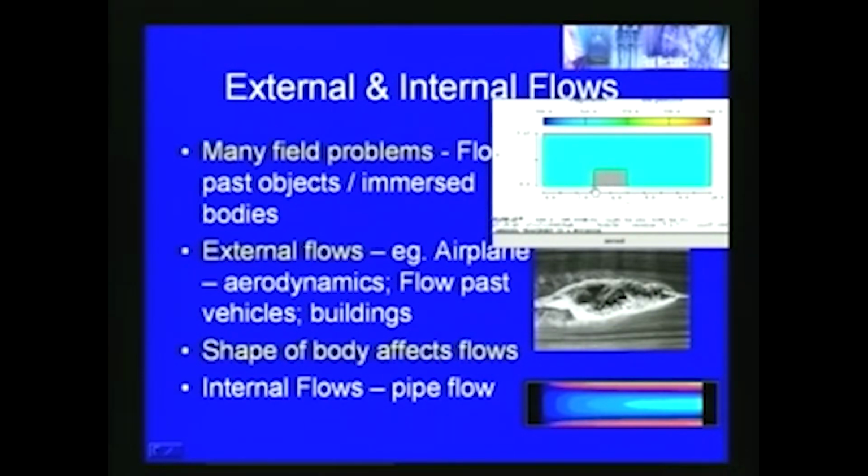Like this, in most external flow problems there is always a boundary layer created, and we have to deal with this boundary layer. When we analyze the fluid flow, we have to deal with the boundary layer, and the remaining fluid flow, other than the boundary layer, we can consider as a potential flow or ideal flow.